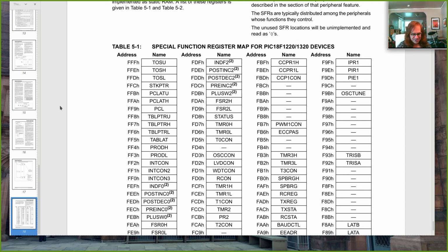The reality is that all of our file register addresses are actually 12 bits. So when we specify an operand, the CPU is actually thinking of our operands as being 12 bits to specify an address, not just 8.